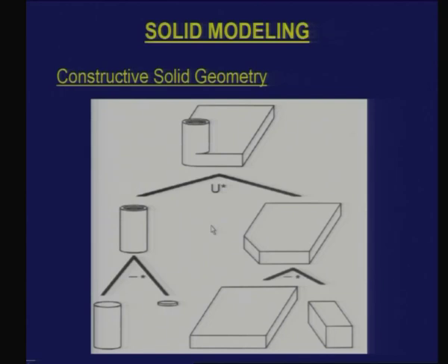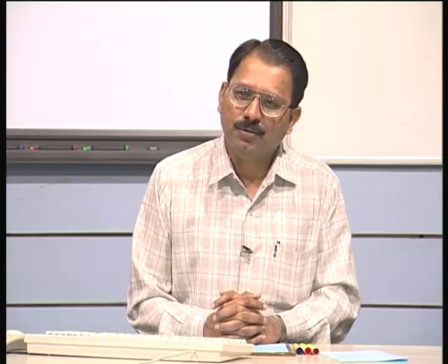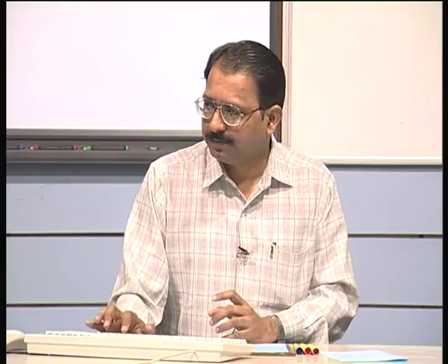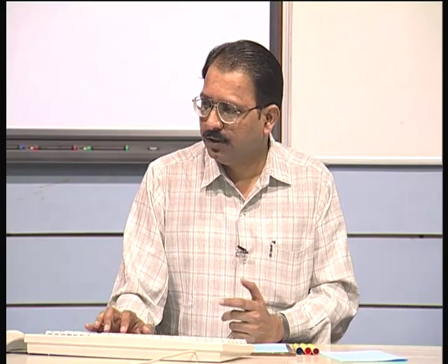This tree may not give me direct information like this, because ultimately one has to look at the final object and evaluate from the final object. We will come back to that. You may have to convert into other representations, and then I can know information like whether the object has two parallel faces. So there are some conveniences in terms of construction and storage, but there are also inconveniences as far as computational geometry calculations are concerned.